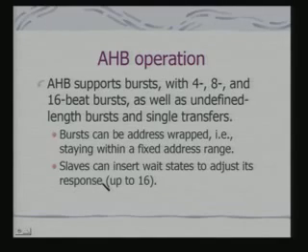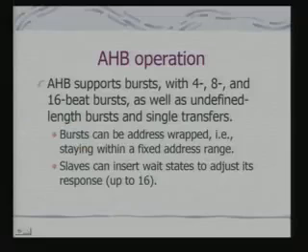In fact, if you remember, we said that if it's a sequential access, you can arbitrate and generate the address once, and the master can have the bus for transferring up to 16 words at one go. It can even be undefined length bursts, as well as simple single transfers.